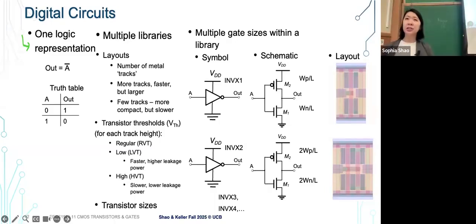When you think about transistors, there are different metal layer stacks, even for, let's say, 16 or 7. For different libraries, there are different flavors of transistor. You can have a flavor that supports more metal layers or fewer metal layers. Those can have different implications on the density of the hardware you construct. We talk about threshold voltage, but even for a particular design or particular node, you can have different threshold voltages associated with the transistors that lead to different behaviors of your circuit.